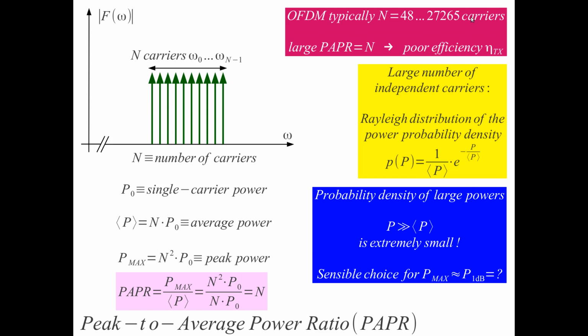And now we have to try to calculate what the distortion is if we limit the power of the transmitter to some smaller value than the value given by the PAPR, the peak to average power ratio. We can get along with much better efficiency from the transmitter with some distortion that's not going to corrupt our signal that much.